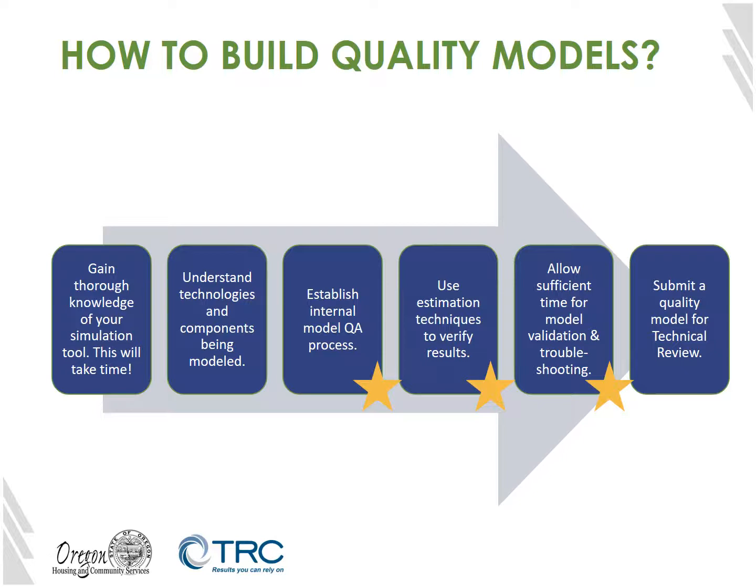Once you've built your model, the process doesn't end there. The most important step we recommend is to develop a thorough internal quality assurance and review process of your own model to verify results and to troubleshoot issues. Energy modeling can be a complex process, and in some software tools may include hundreds of modeling inputs, all of which can have significant impacts on the modeling results.